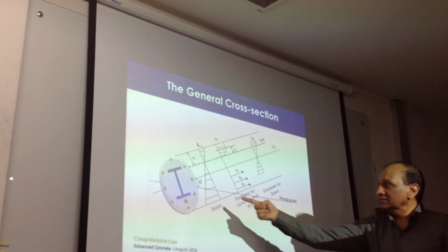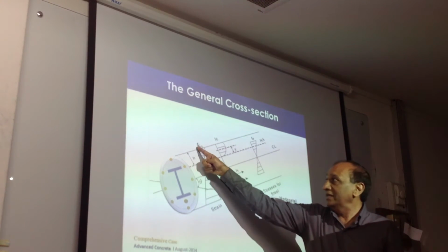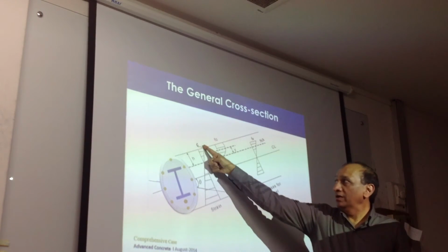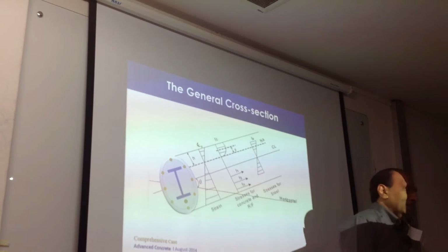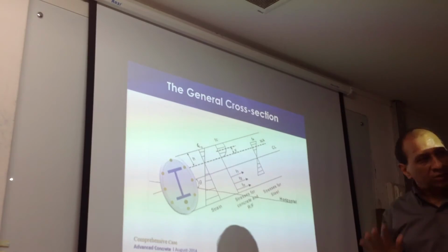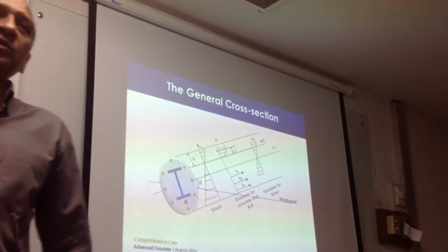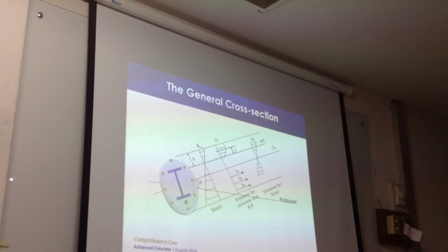We know the angle of the bending and the depth of the neutral axis and the strain profile. Right? Basically, if we know the strain profile and the angle at which the strain profile is there, we can calculate the stress resultants. So please, if you do not understand, I will explain this figure as long as it takes for everyone to understand, because this is the basis of the rest of the theory. If we understand this, then we will go ahead.